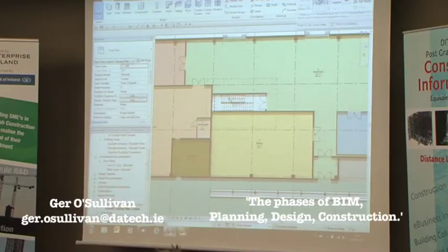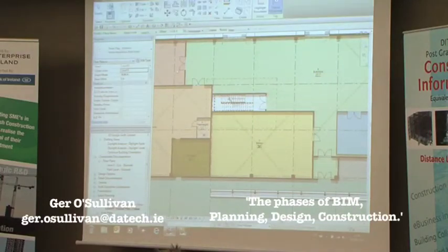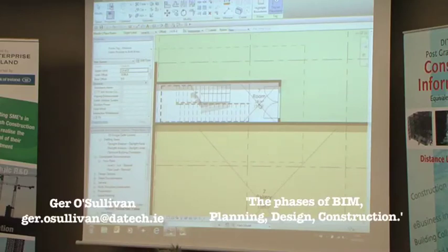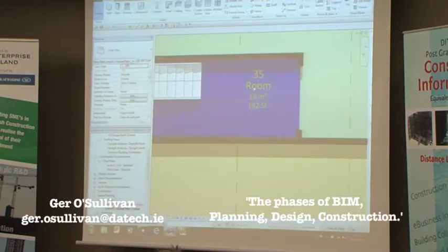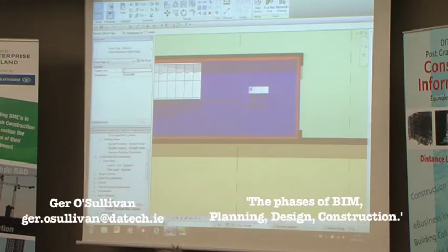So if I want to add an additional room, we can just select the room. We can give it an actual height or a level, and we can place it, as you can see, within the existing walls. So I don't have to worry about the actual area. It's going to be calculated automatically from that. Okay, so it just calls it room. We'll then type in stairwell.